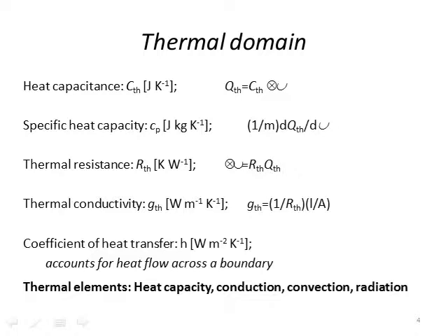And the fan also increases this H so that it's larger so that you can pull more of the heat out of the microprocessor and put it into the ambient air. In thermal elements, then, our heat capacity, conduction, conductivity, convection, the heat transfer coefficient, and radiation. And there are some other symbols that we'll use for radiation that will be introduced a little bit later in the lecture.